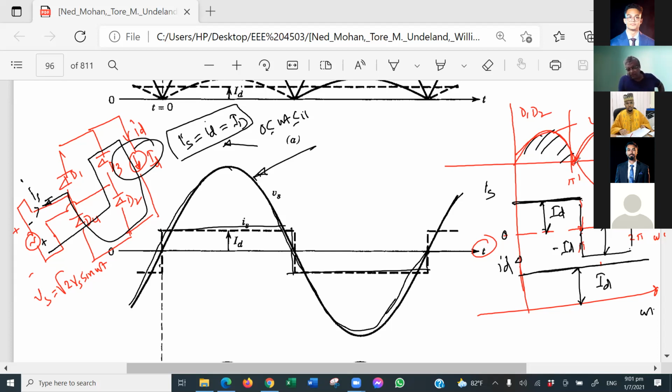When the input voltage reverses to negative, D3 and D4 are ready to conduct, and D1 and D2 are off. So there will be no problem. The current shifting from D1 and D2 will be done immediately, with no delay.